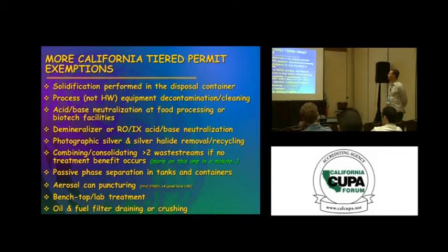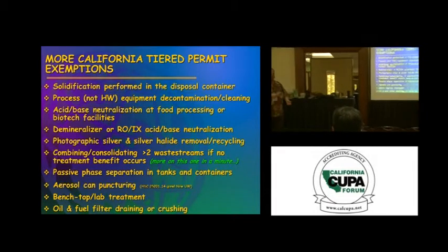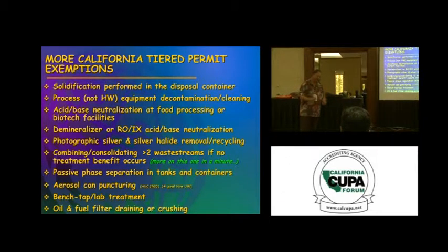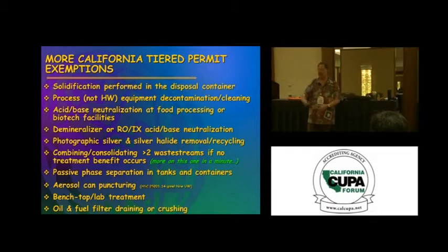Now solidification, remember we talked about, what if you're solidifying so you could land dispose the solids? Is that treatment? Yeah. Is it regulated treatment? Not anymore. So solidifying in the disposal drum, like adding rice hull ash, vermiculite, to solidify the liquid before you land dispose it, is no longer regulated treatment.